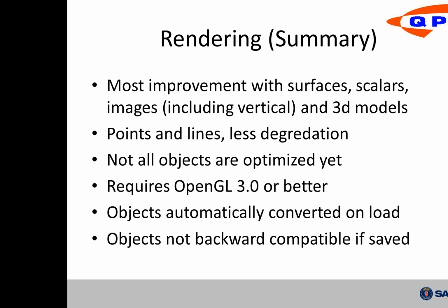Now, if you want to avoid having to do that again each time you load the object, you would have to resave that object. You file save and create a new scene or create a new SD object. However, one thing to be aware of is that once you've saved that in the 7.4 format or created the SD object in 7.4, that object is not backward compatible. You can no longer open that in Fledermaus 7.3 or 7.2. Now, our early beta feedback from this, that isn't something that's important to people.